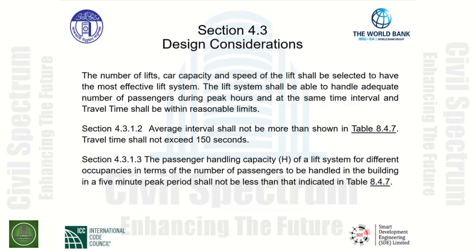Section 4.3, titled Design Considerations. The number of lifts, car capacity, and speed of the lift shall be selected to have the most effective lift system. The lift system shall be able to handle adequate number of passengers during peak hours and at the same time interval, and travel time shall be within reasonable limits.